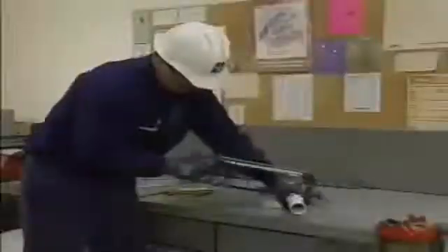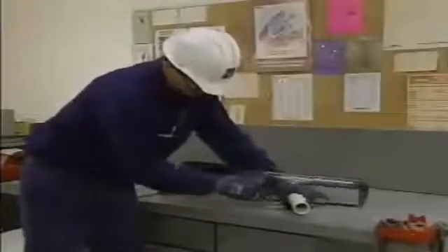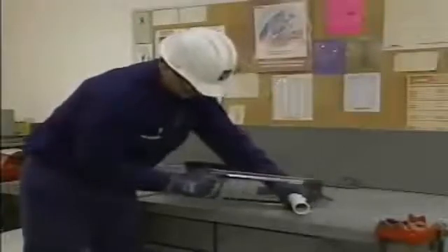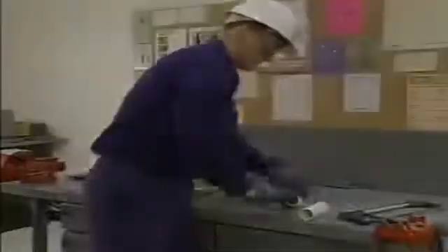Be sure to select the blade with the correct manufacturer-recommended pitch for the pipe you are cutting. Guide blocks are often used to hold pipe steady while it is being cut with a hacksaw. This ensures a straight cut. Cutting is done on the forward motion of the blade, with two teeth of the blade in contact with the pipe at all times. The hacksaw blade should be kept as perpendicular to the pipe as possible, or else the cut will be uneven.